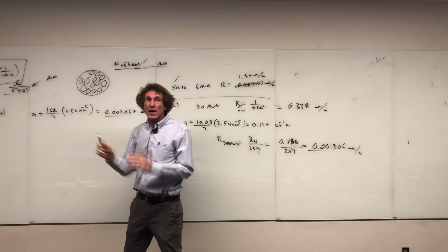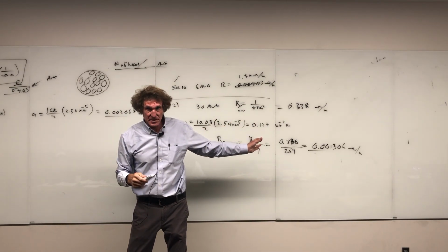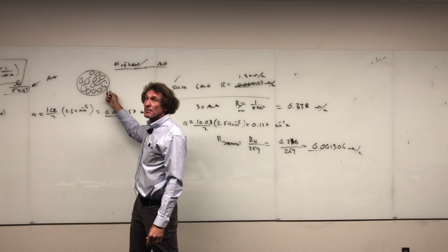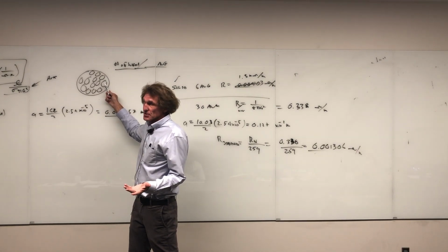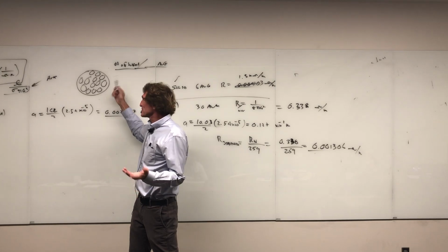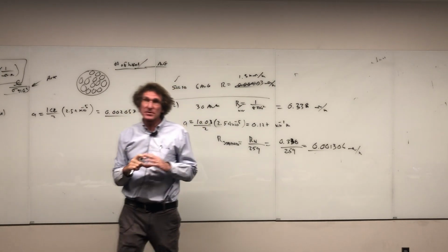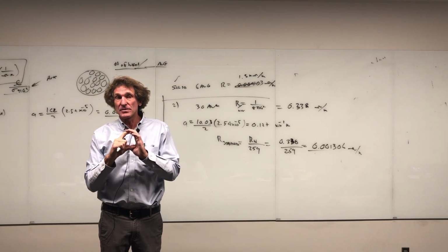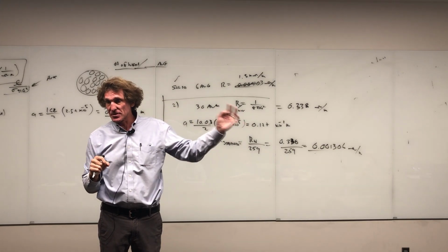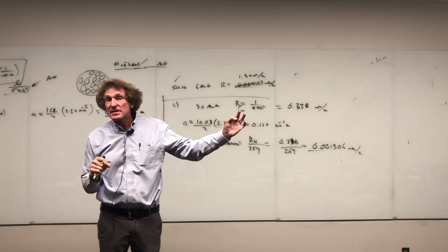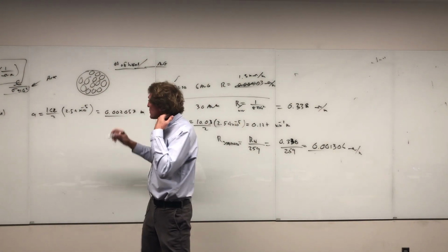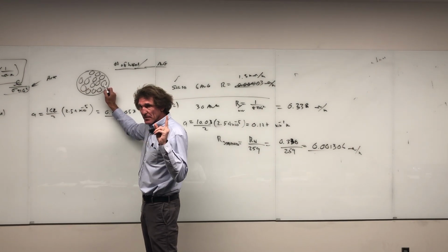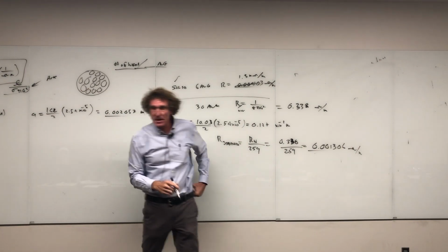However, for a solid wire with the same equivalent DC resistance, the skin depth may be a high frequency problem for sure. As a matter of fact, that's the real thing I should say: if it's a high frequency problem for a solid wire, it may not be a high frequency problem for stranded wire with the same resistance per meter. The reason is you're looking at the skin depth not with respect to all these bundlings, but with just one individual wire. That's the key. Make sure you see that.